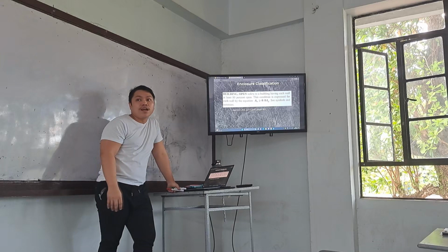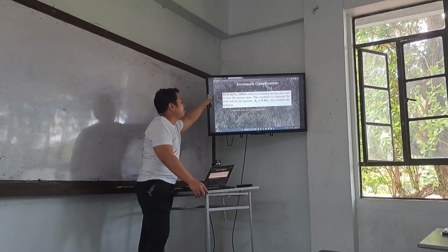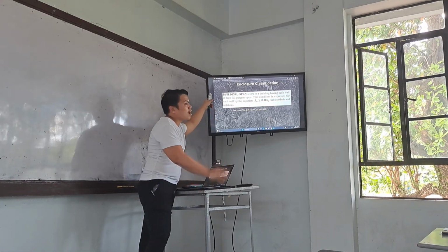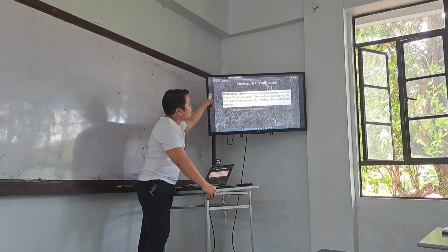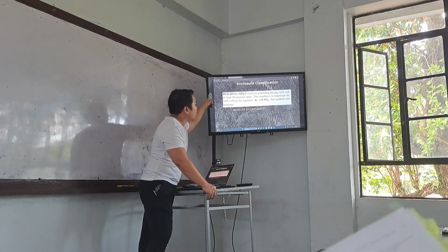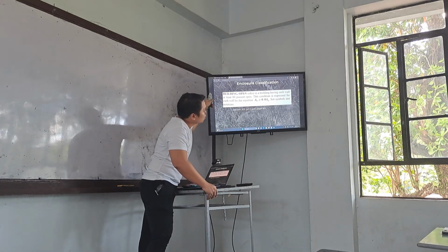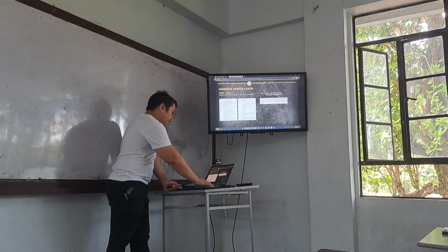That is our first condition: the building has each wall, not just one wall, at least 80% open. This condition is expressed for each wall by the equation A_O is greater than or equal to 0.8 A_G.